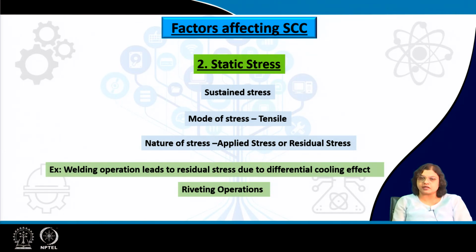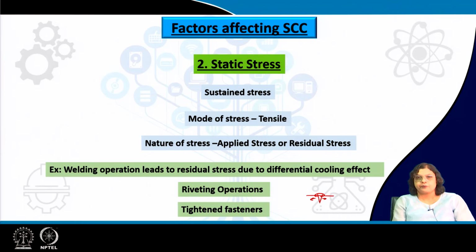But even if cracks are not formed by the riveting operation, the residual stress generated while punching the rivet, particularly at the surface, can lead to early onset of a crack and is reactive to the corrosive atmosphere, provided such an atmosphere is available during service.